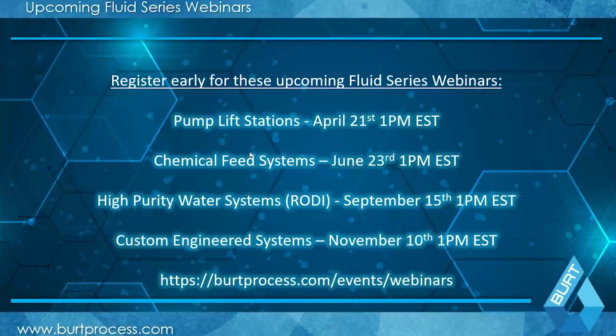Peristaltic I like a lot when dealing with off-gassing chemicals, like if you have to put hypochlorite into your system, say for some form of biologics treatment. That can be very useful. But by and large, I would say electronic diaphragm pumps would probably be the most commonly utilized in the system.